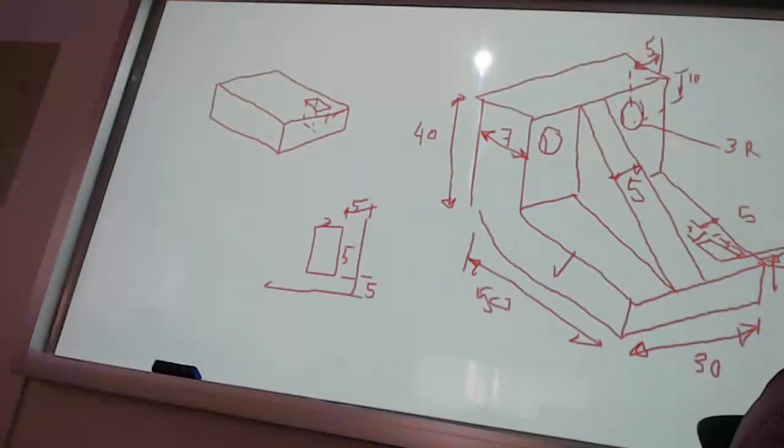Okay, and now you move your XYZ coordinate system and put it on the top. This one will be my X, and this one will be my Y, and this will be my Z, such that I will be able to draw a rectangle. Because usually, guys, as I said, we draw in the XY plane. Somebody might ask, how can we move the XYZ? You did not tell us. I'm going to show you in the AutoCAD, but just let's see how the scenario will go for that guy.